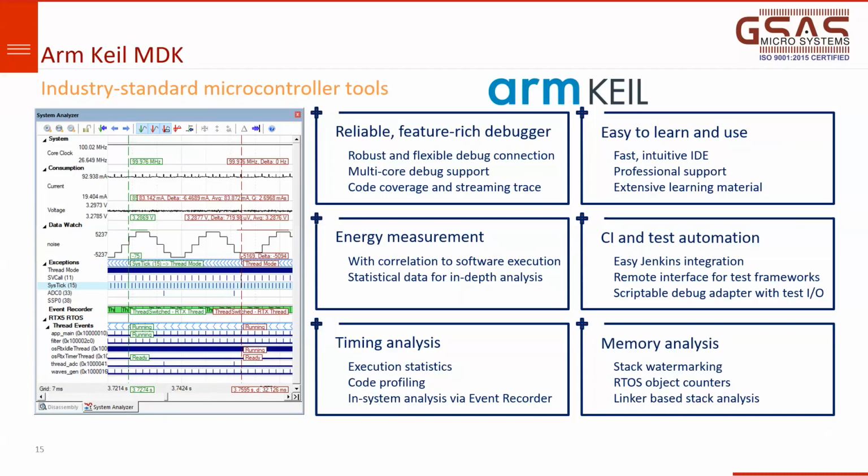With the help of that real-time trace, Keil IDE can also give you code profiling. Code profiling is basically profiling your code: which parts of the code have been executed, what all functions have been executed, and in those functions, which lines were skipped. Usually the lines which have conditional statements like if, else, while are what usually get skipped.